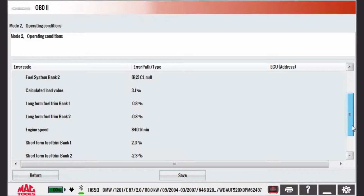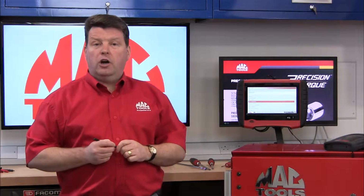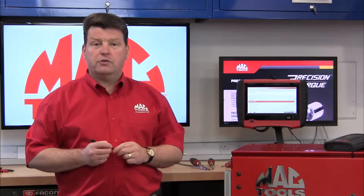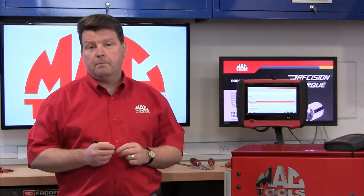Using the scroll bar to the right gives access to the whole list. It looks like this particular code was raised at idle whilst the car was warming up. Now I know when the code was raised, I could clear the code and focus my initial test routine within the warm-up phase, possibly shortening diagnostic time.